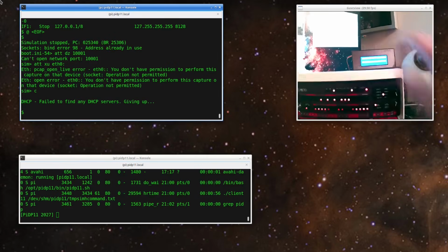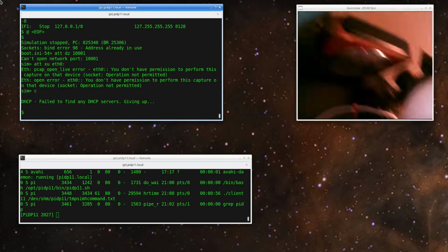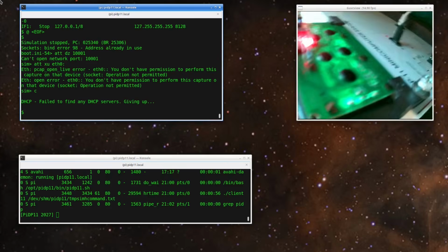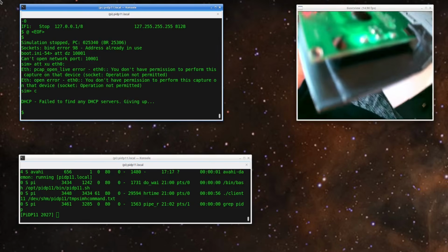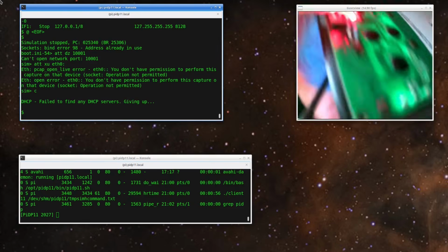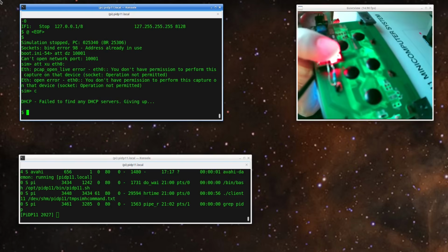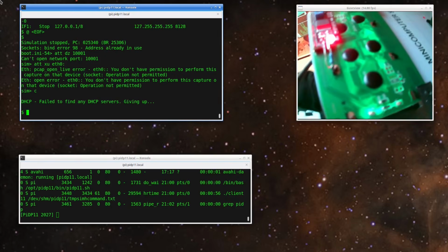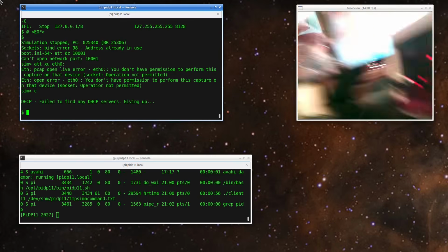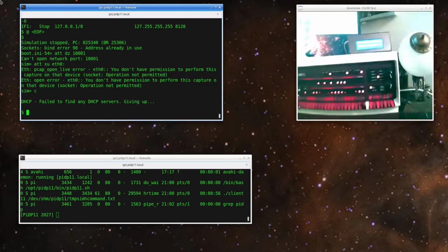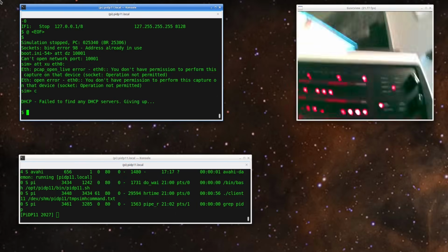Alright, so that sits up there. There's a connector in the back that you hook up to turn on the backlight. If you short that out, the light's really bright, so I put in a variable resistor and measured it out, and about 220 ohms is a nice intensity, and then you can adjust the contrast.